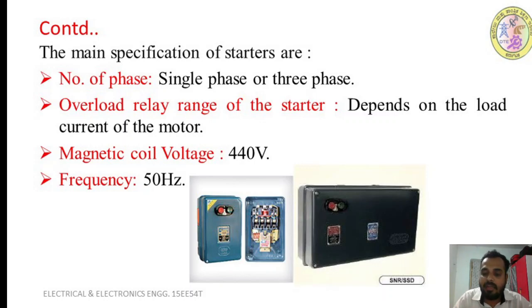So there are different kinds of cables, and how to select the size of the cable depends on our load current. The main switch is also selected depending upon the load current. So ICTP for 3-phase applications, and ICDP or SP switches for single phase applications, we are using. Next we have conduits. Normally we are using flexible conduit systems as well as rigid PVC conduit systems. Rigid PVC from your main board to the starter board of individual machines, and flexible conduit from the individual starter board to the individual machine bed, or to the machine terminals.